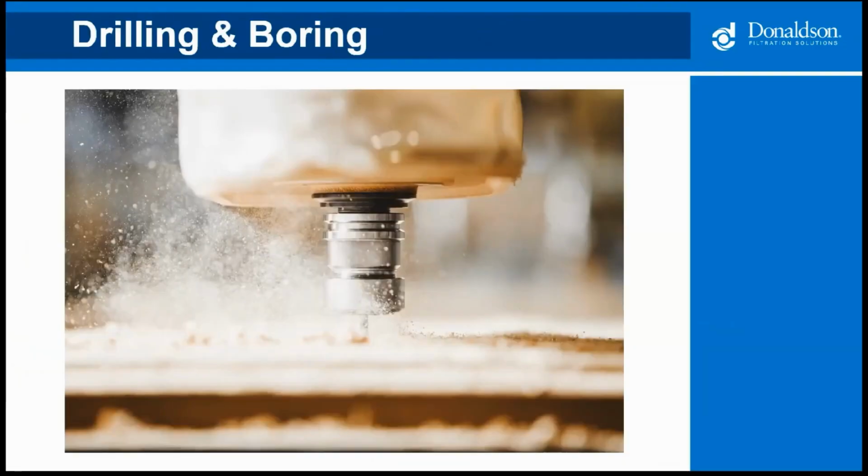Drilling and boring. Drilling is obviously creating a hole in the wood, whereas boring is removing material around a pre-existing hole. Both of these can be challenging for dust collection due to the depth of the hole being produced and the difficulty in getting the suction to the point where it is needed.